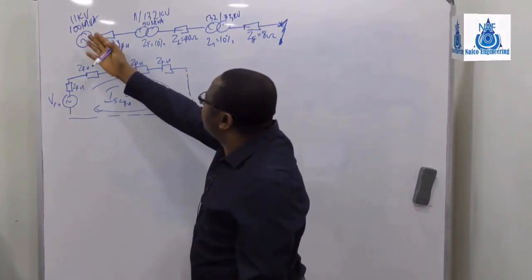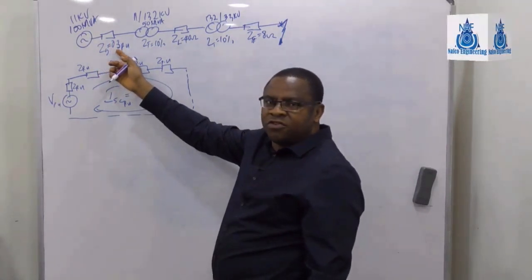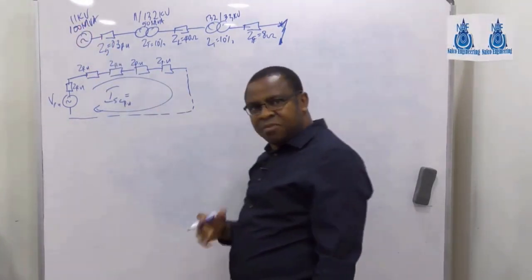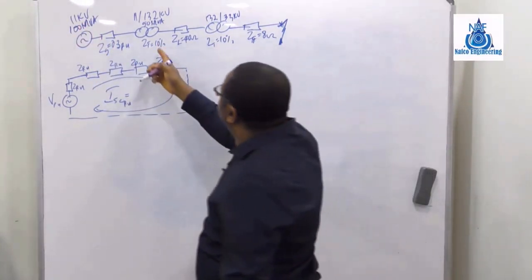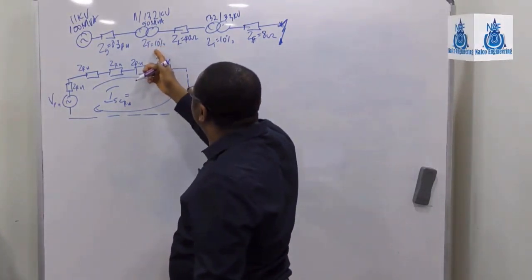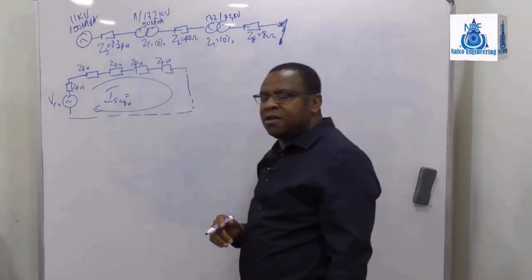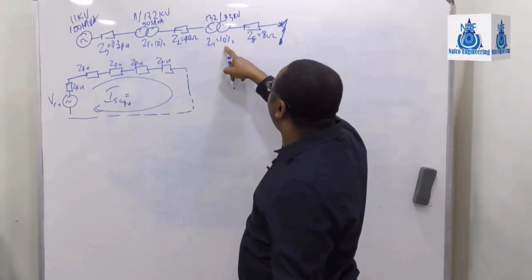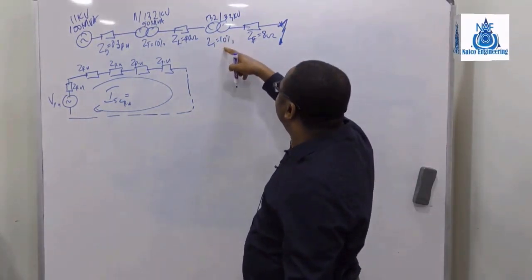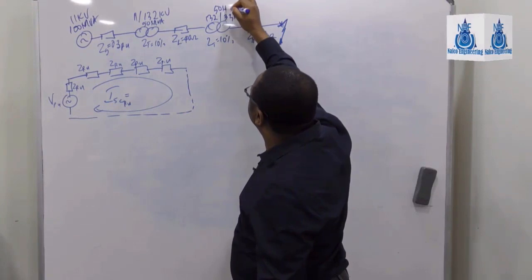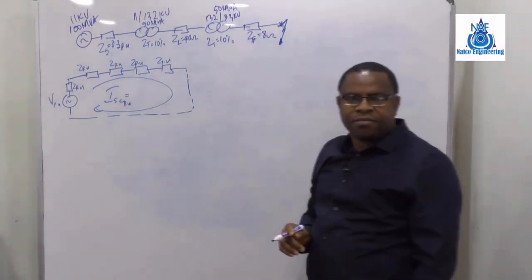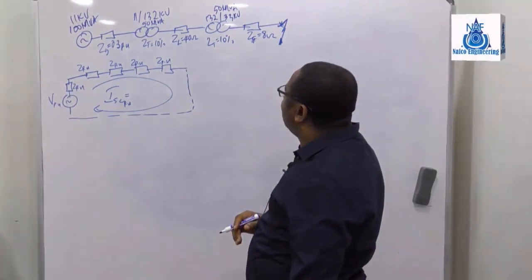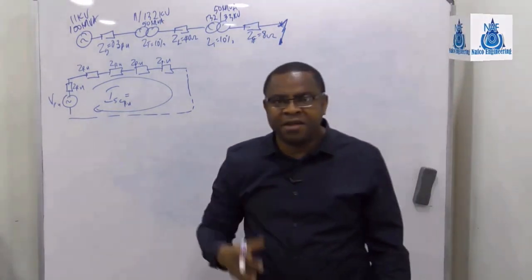Before, if you check here, this is 100 MVA. So the percentage voltage drop based on 100 MVA is 0.3. That's the per unit value, 0.3. But this one, 10%, which is 0.1, is based on 50 MVA. This one is 40 ohms, so actual value. This per unit is also based on 50 MVA, right? All right, and this is in ohms. So we have to choose a common base.